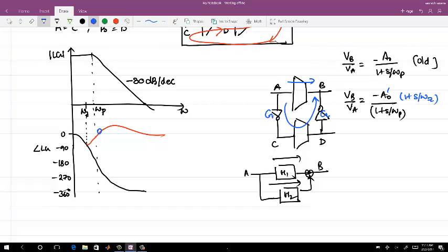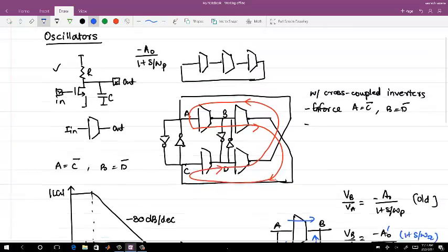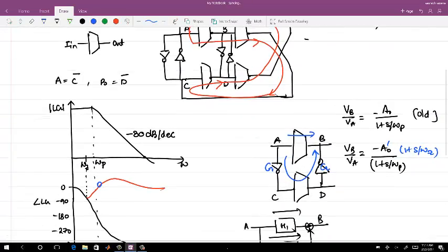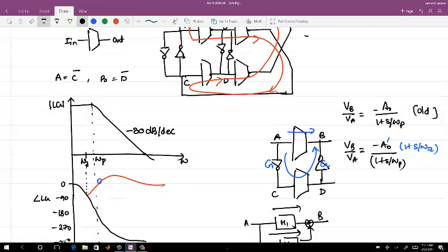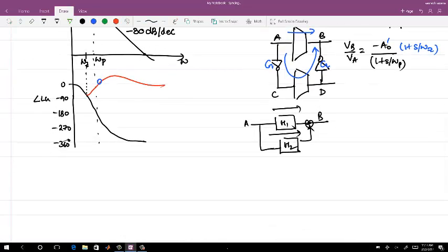Since we have talked that in differential, pseudo differential ring oscillators, you need to have these cross coupled inverters which add a 0. So it is doing two things. It's adding a 0 and it is maintaining the phase relationship of 0 and 180 degrees. Both are important.